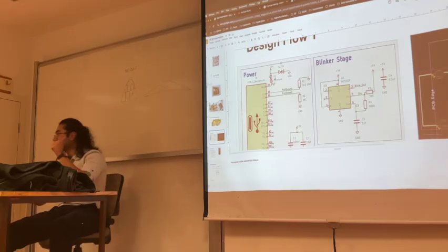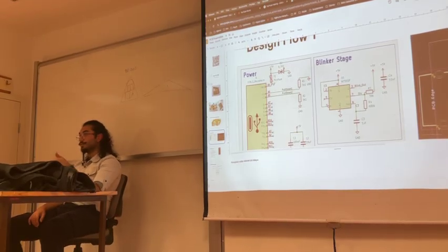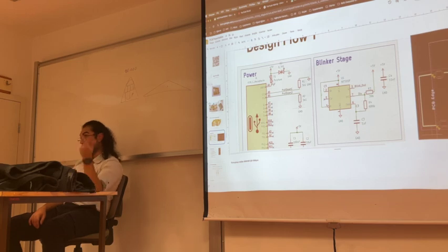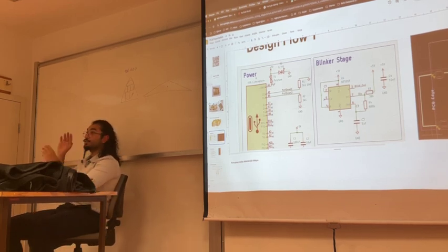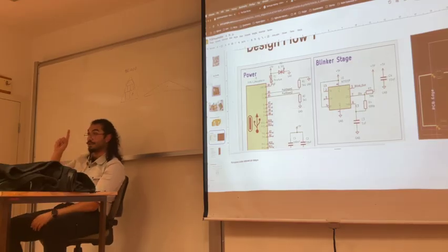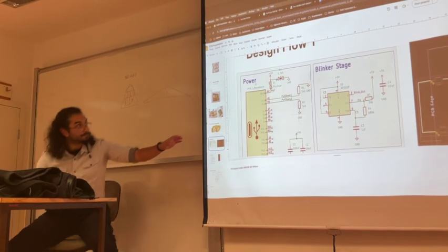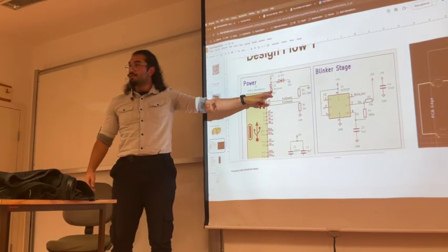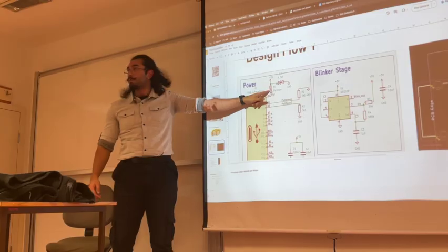Okay? And a TVS diode is the same thing as a fuse, not structurally the same thing, but conceptually the same thing, but it is used for voltage. If your voltage gets really high, your TVS gets rid of it. You can think, if your current increases too much, this resistance becomes infinite, so this is an open circuit.